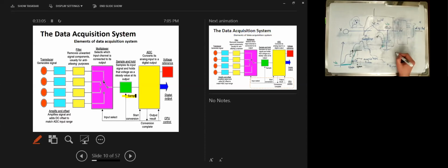We need the time that is required by the converter to convert the collected sample, which is the conversion time. And we need to wait for the acquisition time in order to allow the capacitor to follow the input signal, to be close to the input signal. The shorter this time, the larger the error that you will have in the acquisition. The longer the time, the less the error. However, what is the effect of increasing or decreasing this time?